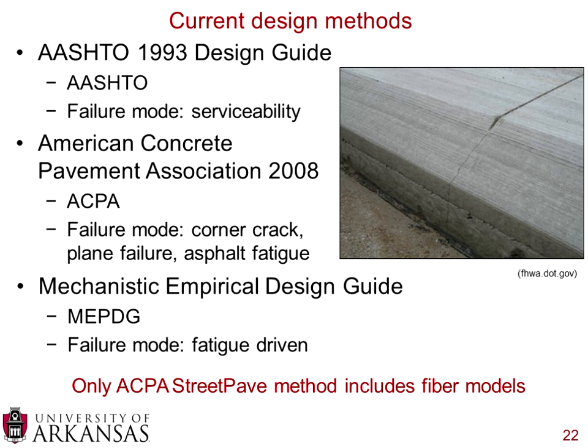And you can see this nice picture here on the right. You have an existing concrete pavement with a concrete overlay. This is from FHWA, and you can see that little slope on the side of the pavement is the safety edge. That's to ensure that as cars go to the left and the right, if they happen to run off the pavement, it's not just a 6-inch drop, it's more of a slope where cars can safely go on and off the pavement without causing any severe problems. It's obviously not encouraged, but it has helped with significant accidents.